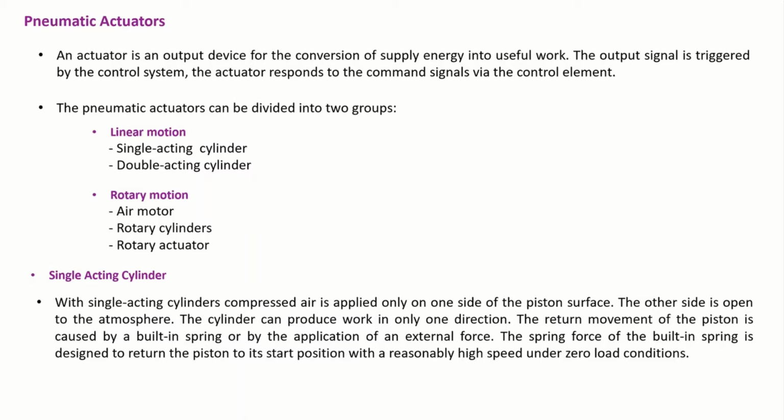So what is a single acting cylinder? We already saw how the single acting cylinder works inside FluidSIM, and also covered a bit of its application. When we talk about a single acting cylinder, the compressed air is provided from one side of the piston surface, and the other side is open to the atmosphere. So the cylinder can produce work only in one direction.